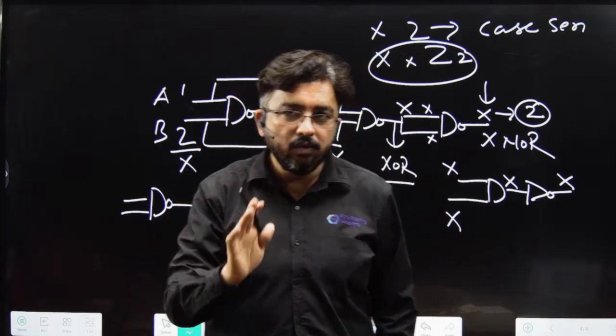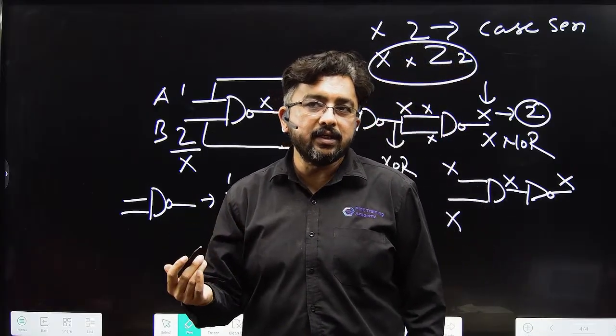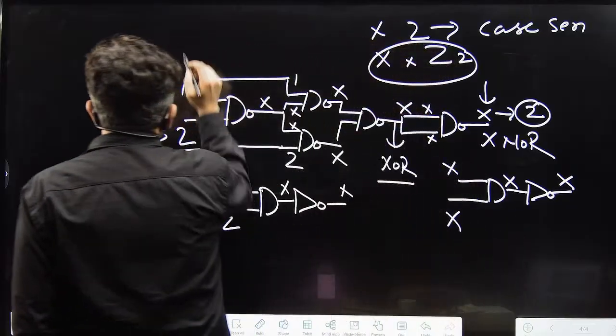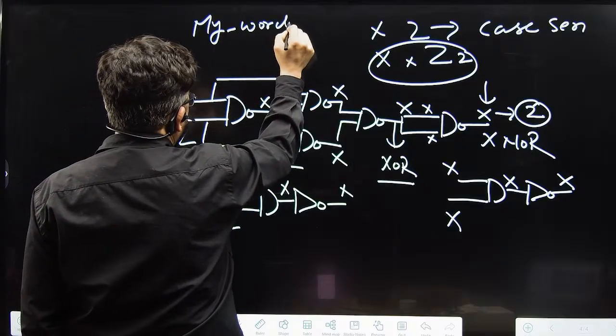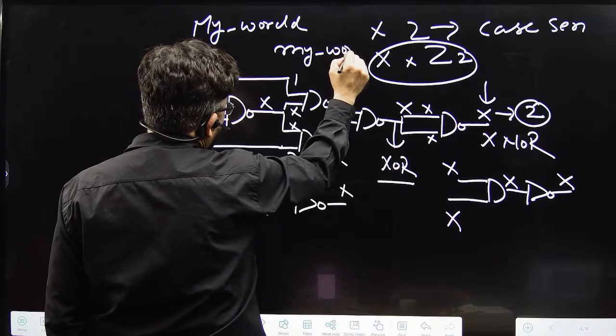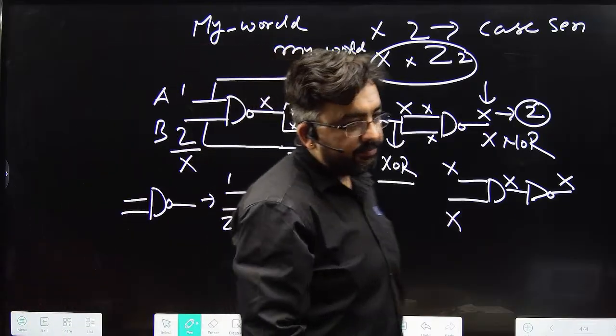But the whole Verilog syntax as well as the identifiers are case sensitive. So if you are using capital My_Word, and somewhere in the same program you are calling small my_word, then this will give an error.